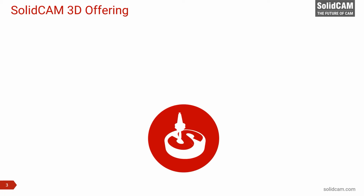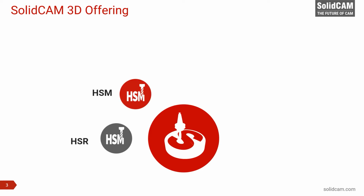So what are we currently having in SolidCAM 2021 as far as 3D milling is concerned? We have HSR, which is 3-axis roughing, the generic roughing. And then we have 3-axis HSM, which is the generic high-speed machining functionality in SolidCAM. And then we have the new generation Turbo HSR and HSM, which is basically the new generation roughing and finishing operations in 3-axis.